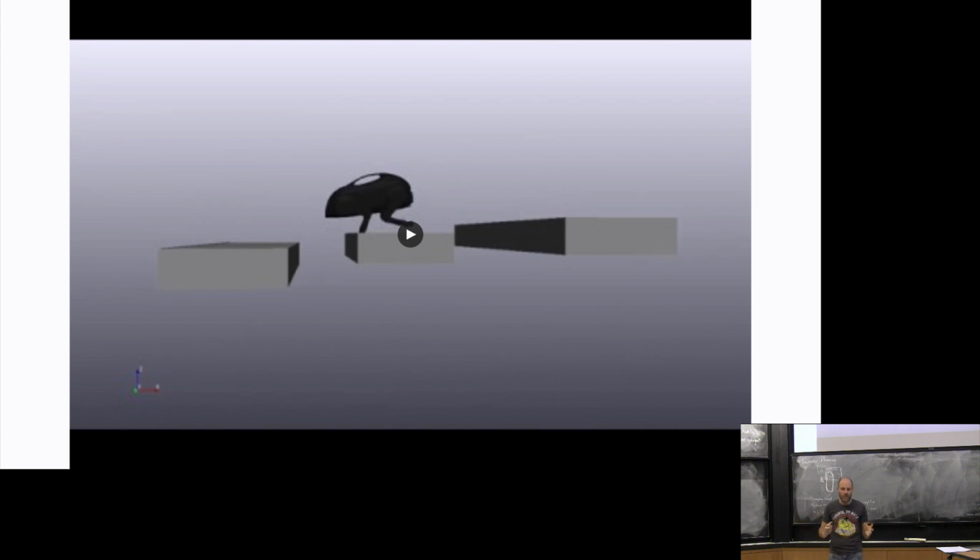So what happens is we plan with this sort of hand of God that could potentially stabilize the robot. And when we take that away, if our relaxation was too loose, then it could be that there was not actually a feasible trajectory there. So there's a balance between how expensive that optimization is and how tight those regions are.